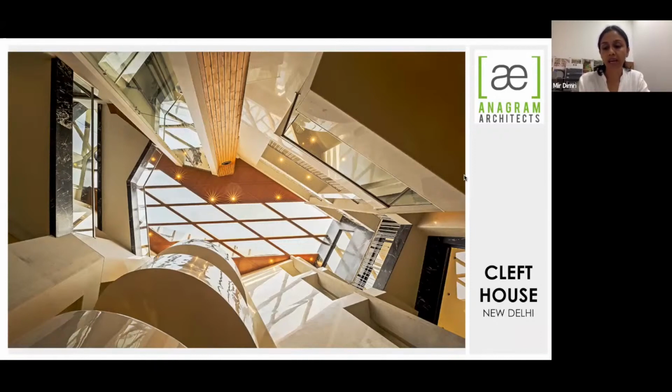Now, we have atriums in a lot of houses in Delhi, but over here in a small tight plot, if you cut out an atrium right in the center of the building, then the terrace becomes really unusable, because you're dividing that entire space into just a peripheral width all around the plot, because the center is all empty. So in this project, we decided to cover the atrium with glass, but glass strong enough so that you could walk over it. That completes the entire terrace floor plate and it can be used for whatever, even a party or whichever other ways the people want to use their terrace.